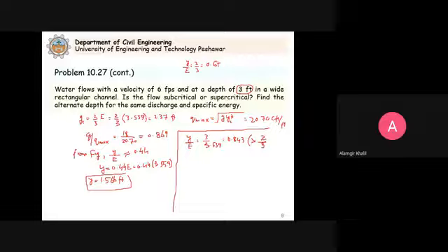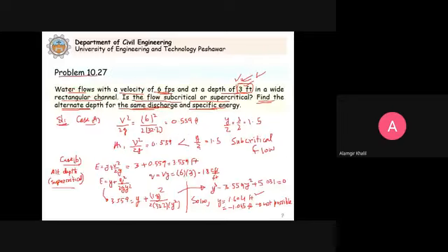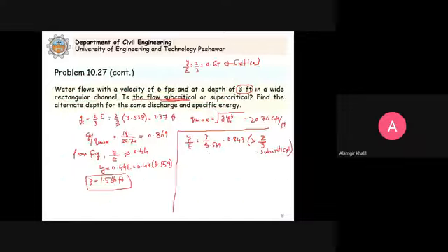So when it is greater than 2 by 3, what is this condition? This is the condition for subcritical. Even your case A can be seen from here. See, this is subcritical, greater than 2 by 3. You see, this is for critical, this is the situation for critical, which we already proved before. So now this y by e is 0.843, greater than this, it means that in the first part, the flow is subcritical. Alternatively, we can prove it like this. We proved that here V square by 2g is less than half of the depth. So we say subcritical flow. But from here, you can also see that this 0.843 is greater than 2 by 3. So we have subcritical.